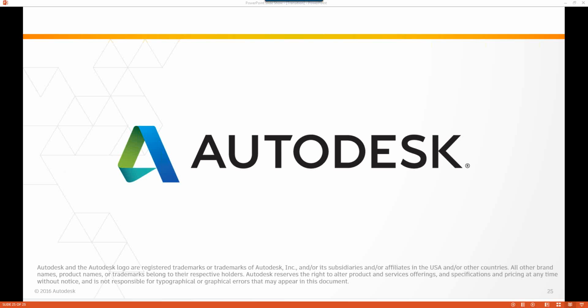MES is a little bit of a tricky beast. MES kind of encompassed a lot of different things in Simulation Mechanical, from just nonlinear statics to nonlinear materials, transient dynamics, and I think one of the big differentiations that it had there was the ability to do kinematic elements. I don't know how many people are actually using that, but I think really being able to just take a part out of the model, treat it almost like a rigid element, and do some sort of a nonlinear transient kinematic solution.